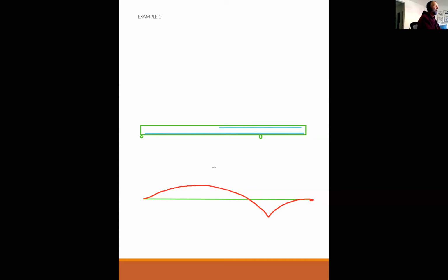Okay, so I think I have 2 parts to the answer to that question. The first part is that theoretically, you could just put the bottom steel where you have positive bending, and you could just put the top steel where you have negative bending. These bars don't have to go all the way out. And that's going to be a lecture in a few weeks, about how you can develop these bars and when you can cut them down.